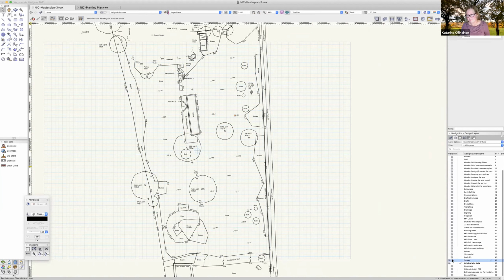You can see I have them all here. This can also be 3D polygons giving the contours of a site. It doesn't matter, any kind of level data you can use here, but it has to have the actual Z values. So I select them all and go up to Landmark, Create Site Model from Source Data.